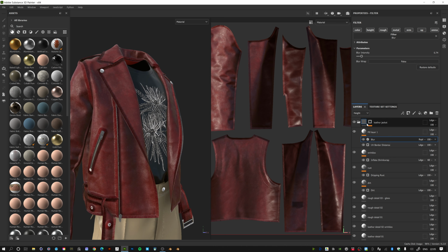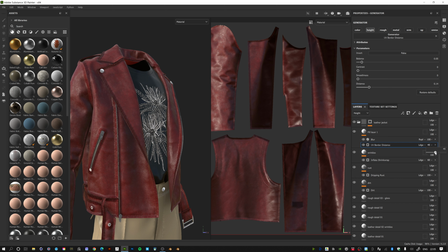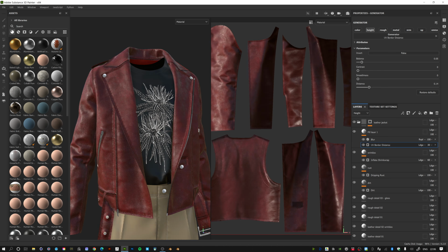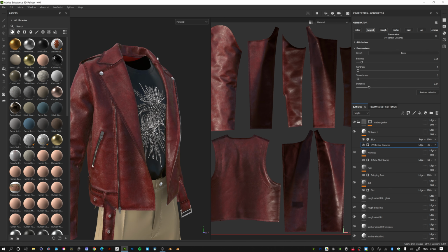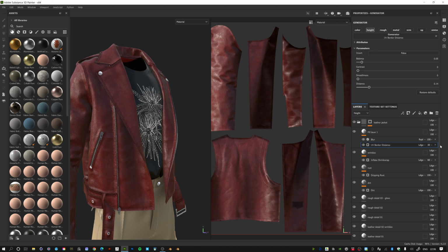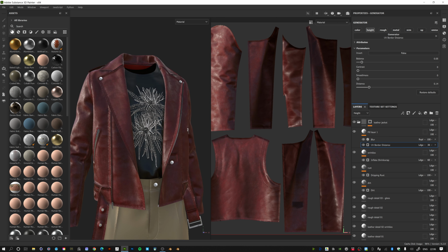And then I'm going to go to the height channel. So I'm already in the height channel here. And for the UV border distance, I'm just going to select here and bring down this value from 100, maybe to about 20, 30. And rotate this light to see how this thickness is visible. So I'm really looking at the color construction here and at the edges to see how this thickness is looking. Maybe I'll increase this amount a little to about 36.